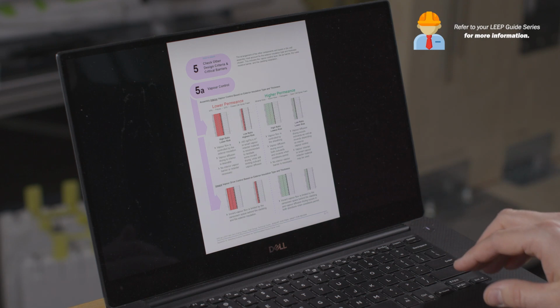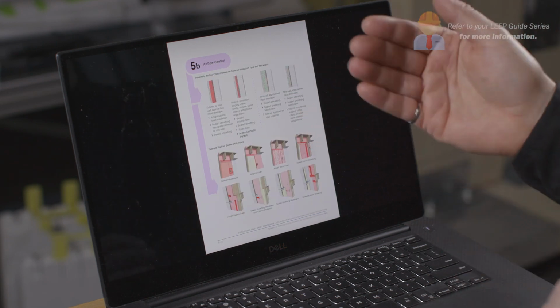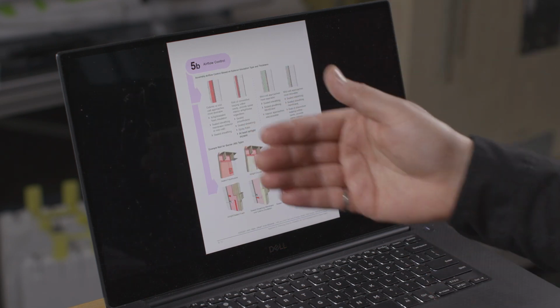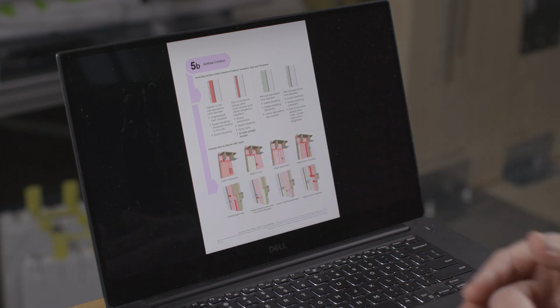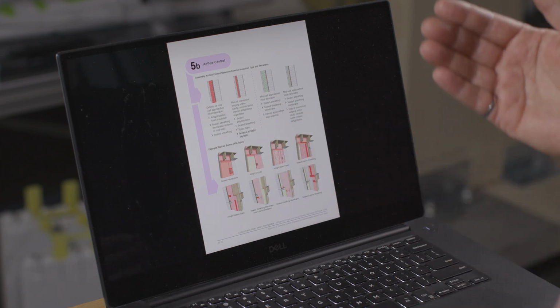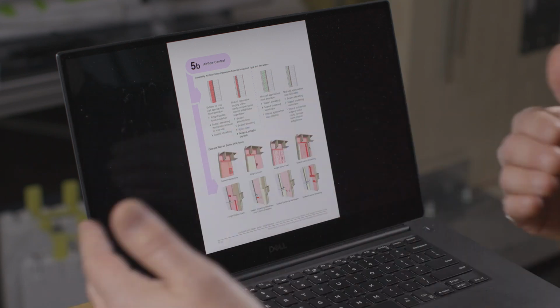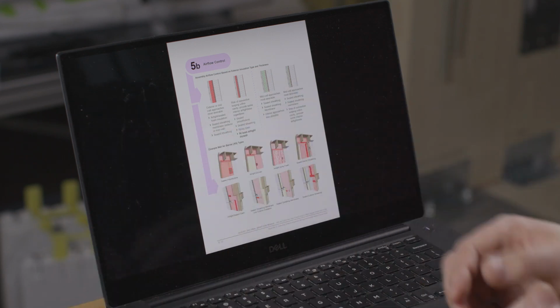And that's entirely what this table is walking through. So I encourage you to walk through some of your own examples here to look at high and low ratio. Both can work. And there's likewise vapor permeable insulation guidance for high and low, and a number of specifics come through this. So vapor control is covered. Air barrier and ideal air barrier placement is also covered in here. And then we also talk about different air barrier types, right? If you're placing the air barrier on the inside or the outside, you have a lot of choice. And this talks about where the air barrier ideally would be in those assemblies as well.